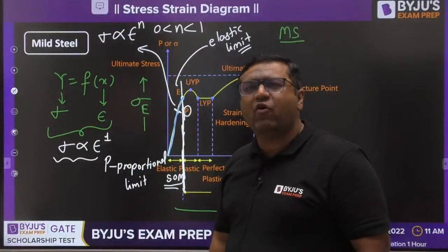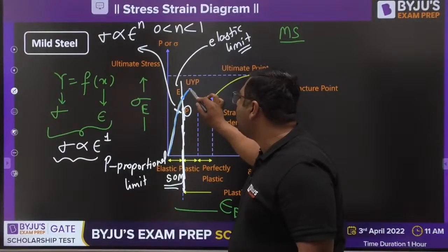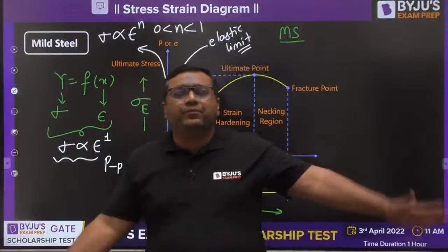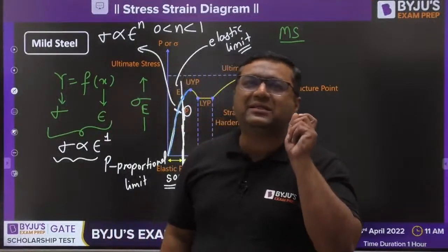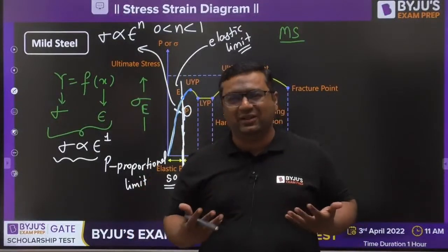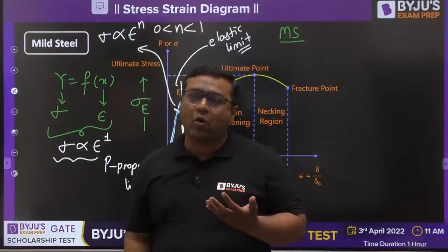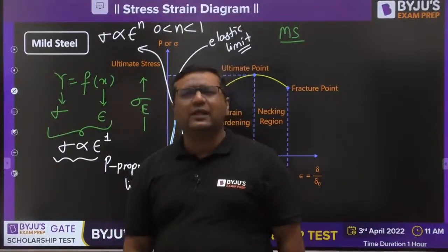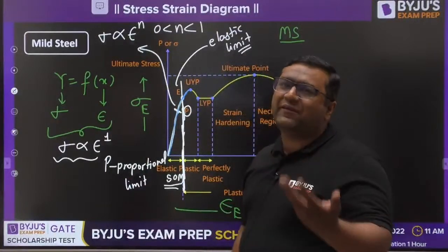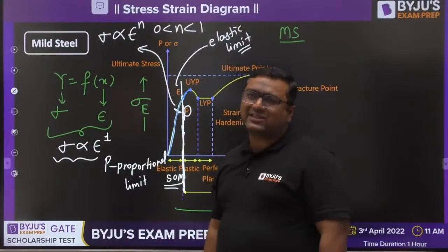Why stay before this limit? So when you cross the limit, my dear, the material no longer remains elastic, because after the elastic limit, the bonds are going to start breaking. And once the bonds start breaking, they no longer have any connection, there is no such attraction or repulsion which we were talking about till now between electrons and nucleus, because they are away from each other and away from the reach of each other. So because of that, this time you enter into the plastic region.